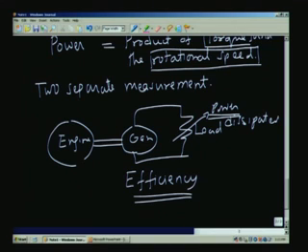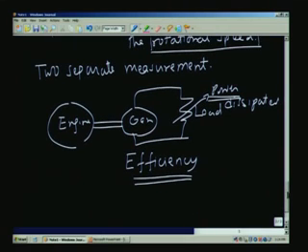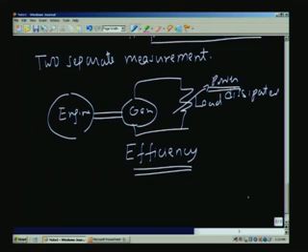So, in the case of direct measurement, even though it is possible, the power dissipated through the load can be directly related to the power generated from the engine if we know the efficiency of the intervening items. So, in this case the generator efficiency and then the coupling efficiency, there may be friction and other losses and so on. So, those are the problems which make it difficult to use this method, even though for rough measurement it is perfectly logical to make the measurement in this particular form.